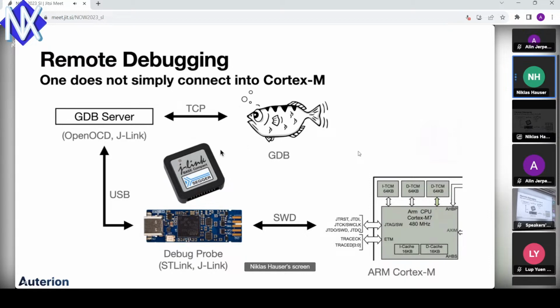And now you can already debug your microcontroller in the command line, which is not very user-friendly. So typically this gets wrapped by the GDB machine interface inside your IDE. And that actually then shows you a visual representation of the entire debug state, where you can set breakpoints, you can single step through the lines. It's much more user-friendly. But it's not scriptable. So we're not going to do the IDE route. We're going to go through the command line, and I'm going to show you a couple more tools, how to make that more useful, and also how to script it from the outside for unit testing and for CI.